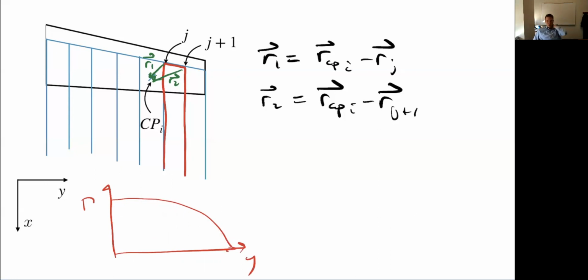Important thing to note if you do that, the control points don't go in the middle of the panel. They go in the middle in theta space. So if you remember how to do cosine spacing, we use that cosine transformation we've seen. We take linearly equally spaced directions in theta, and then we transform it. We do the same thing with control points. We define these nodes at equal spacing in theta, and we define the control points halfway between them, and then we take the cosine transformation.